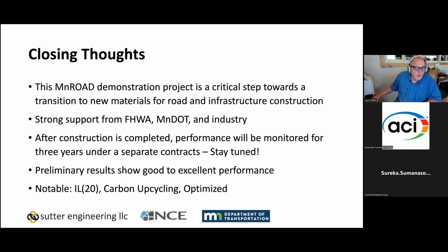But all the preliminary results are good. Some are performing very good, some are performing good, but there's really nothing out there that we're having heartburn over at this point. And the notable ones I'd like to point out were the 1L20, the carbon upcycling, and the optimized mix. The 1L20, as I said, that was a true 50% clinker mix, and it's performing very, very well. Carbon upcycling, in terms of actual placements, was probably the nicest looking slab when we got done.